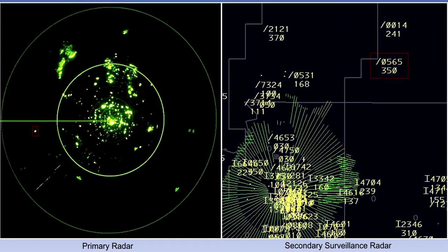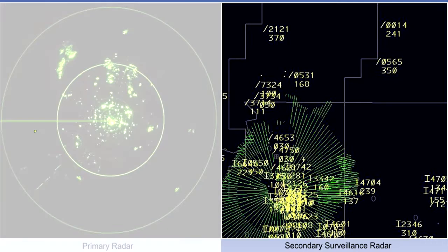Remember that secondary surveillance radar works by sending interrogation radar signals to aircraft transponders. These interrogation signals specify the type of information a replying transponder should send, for example, aircraft flight level, speed, heading, etc. Where secondary surveillance radar is used, aircraft may be identified by a radar controller by using any one of the following methods.